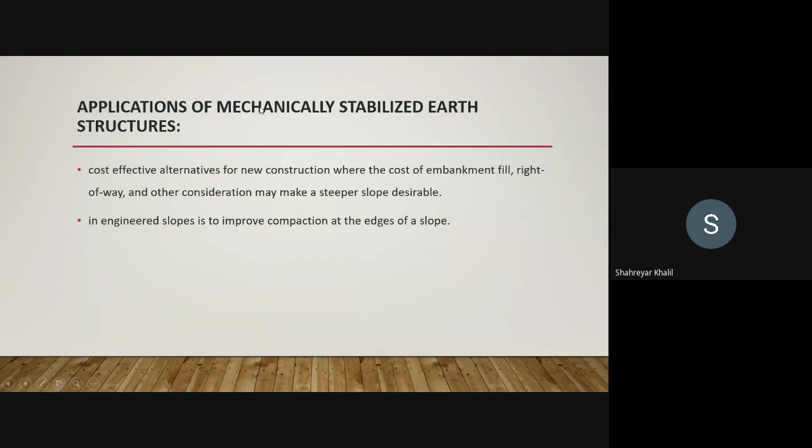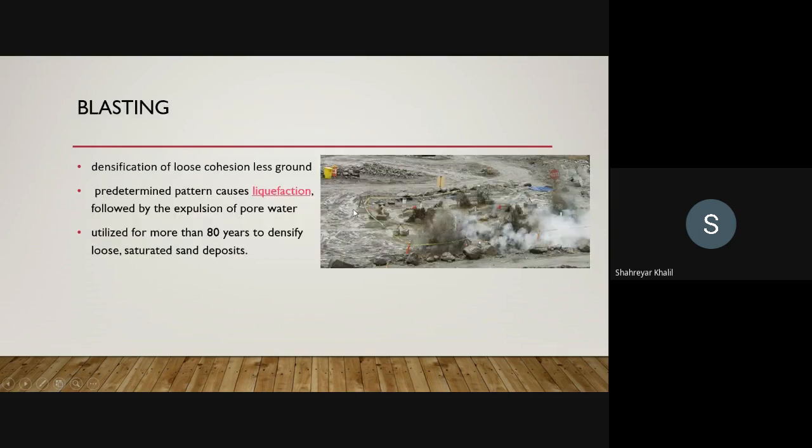Similarly, this is how it is to be applied. This is also a cost-effective alternative for new construction, where the cost of embankment fill, right-of-way, and other considerations may make a steeper slope desirable. An engineered slope improves compaction at the edges of the slope.